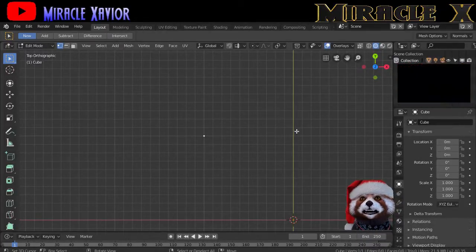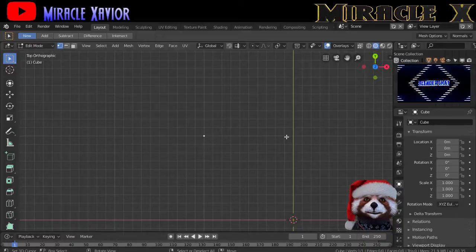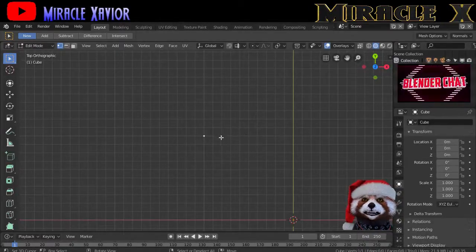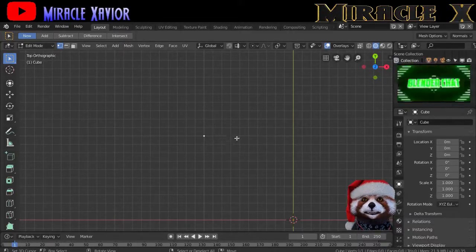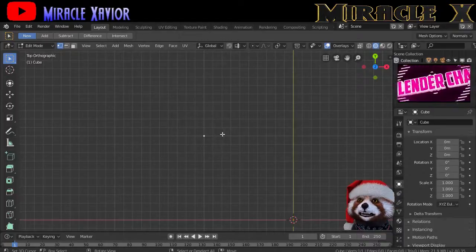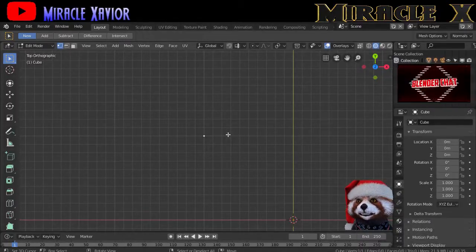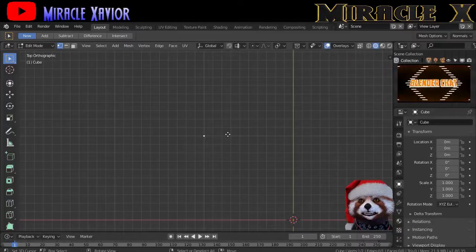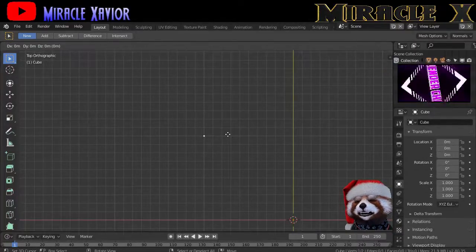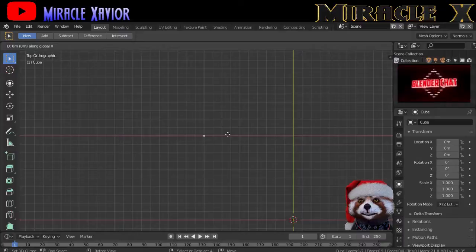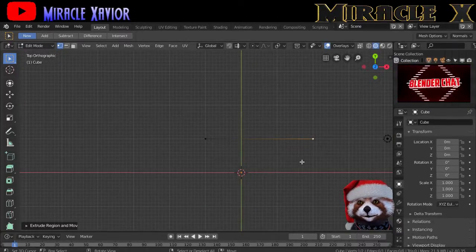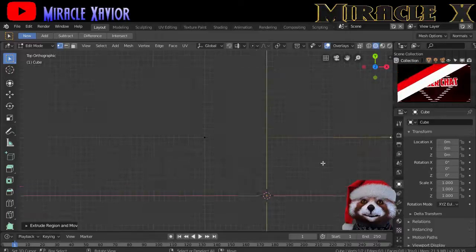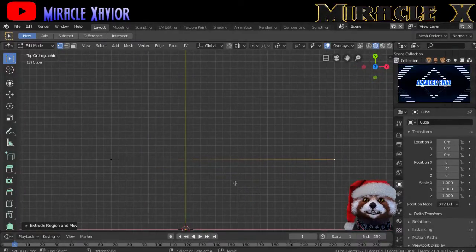So you say X and say 1, 2, 3 cubes to put a line to go in there. But for Blender, you extrude by pressing E, and then if you extrude along X and you press 3, you get the same line. See, something simple like that.